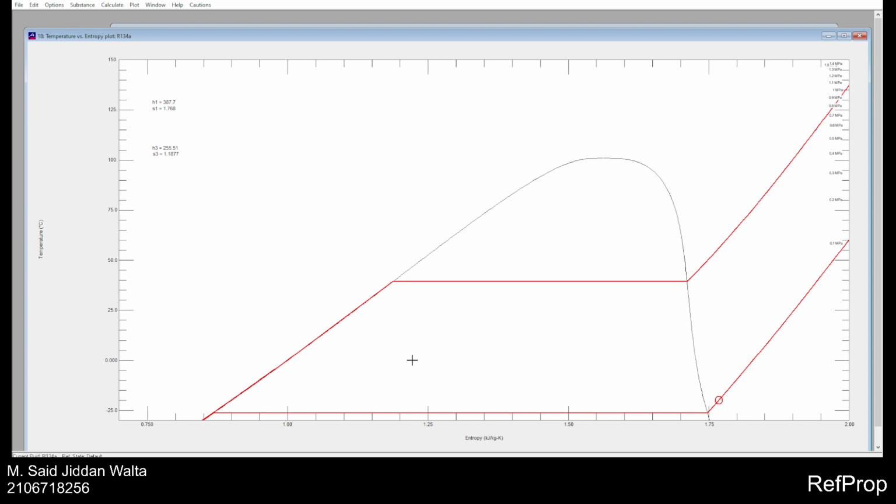Now, as we have previously mentioned, from this starting point of point 1, it is isentropically compressed directly up to point 2 if the compressor is 100% isentropic efficiency. However, the problem states the isentropic efficiency of the compressor is 85%, so that the actual point would be either more to the left or to the right of this directly above point.